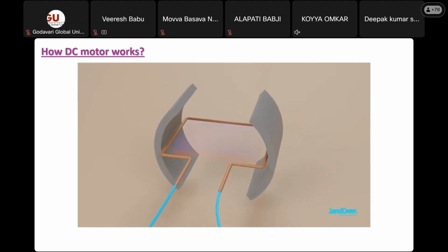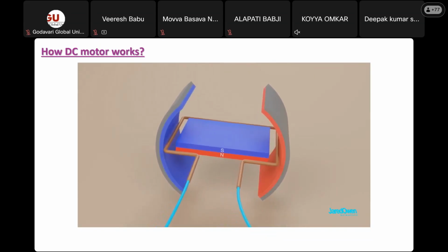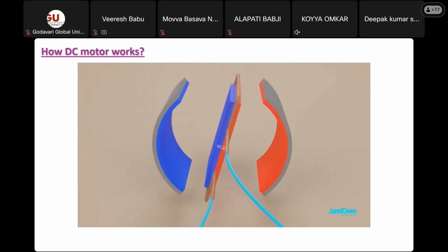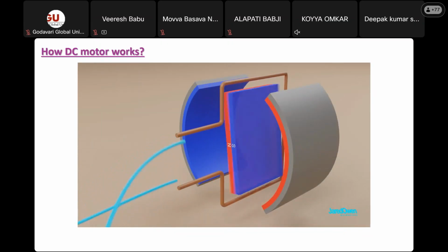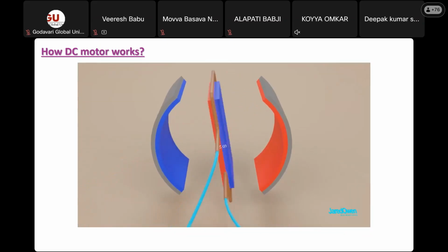This time you can think of the electromagnet as flat like this with the south pole pointing up. Now the armature will spin until opposite poles are lined up. We can keep it spinning by switching the wires just like we did before. But this is a lot of work to sit here and manually switch these wires.